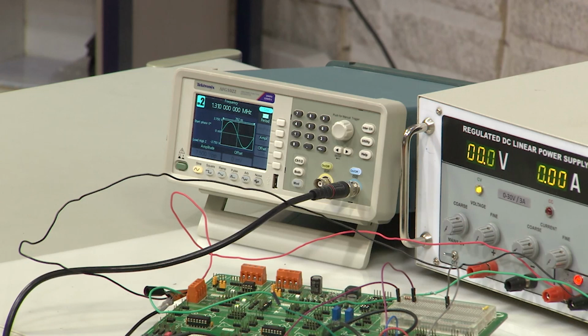You can see it very clearly, right. For a 2.2 gain, we have a range of 500 kilohertz. The product is around 500 into 2.2, which is around 1100. For the second circuit, the gain is 1 and the range of frequency is 1.1 megahertz, or 1100 kilohertz. Again the product is 1100 kilohertz into 1, which is 1100. There also 500 into 2.2 is 1100. So you can see that the gain bandwidth product remains the same, and both aspects, the gain and the frequency, will affect the range of the op amp.